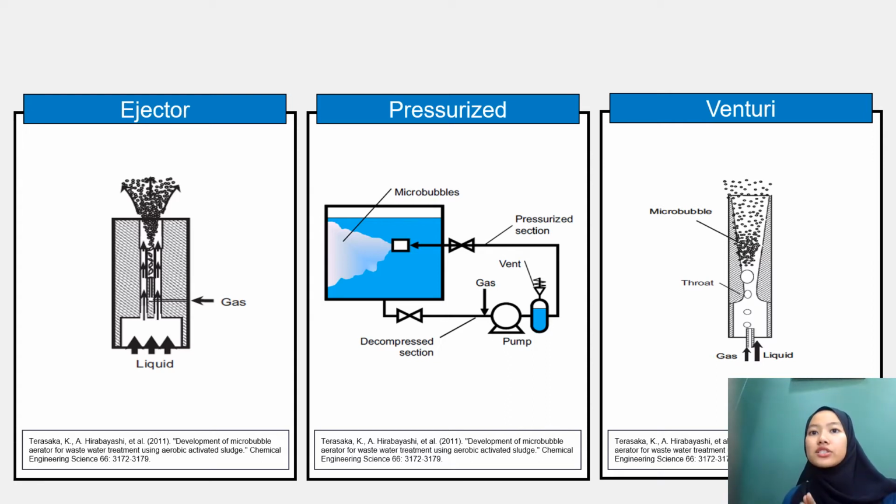Thus, by the energy conservation principle, the pressure becomes negative, and the air is sucked automatically through the porous pipe embedded into the pipe. The air is then broken down into microbubbles. But the difference between this type of MBG and ours is the presence of the hydrophobic PTFE membrane that wraps around the venturi type MBG.